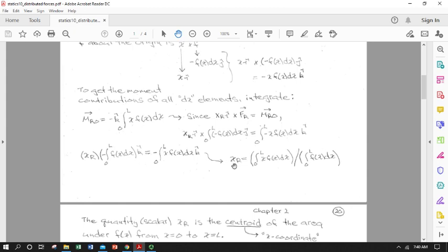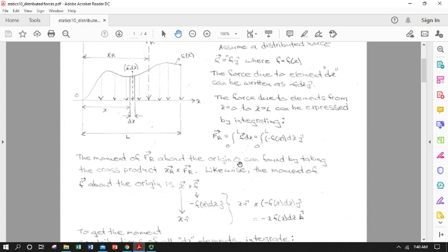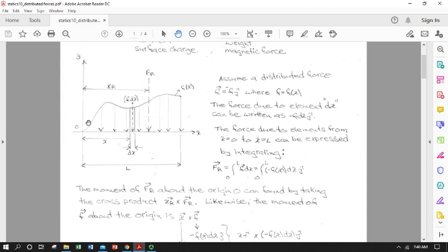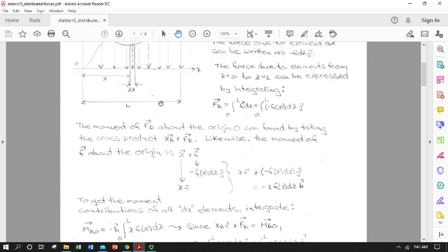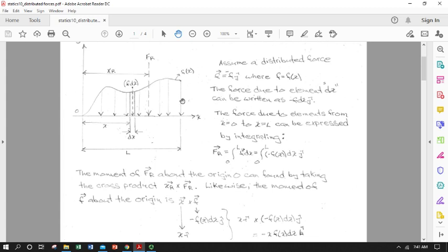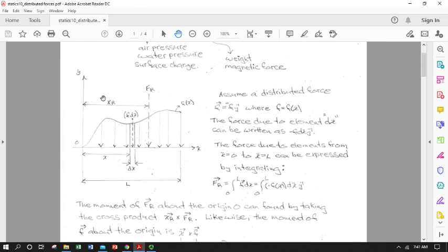So you have applied the definition of moment, and you have added up the contributions of a distributed load, in this case force per unit length, over the entire length of application to get a total force resultant. Then you've looked at the moment due to each little bit of that force distribution, and you've added up all those bits of moment using this expression over the entire length, and then divided them. Sum of the moment equals the moment of the sum to get your x sub r.